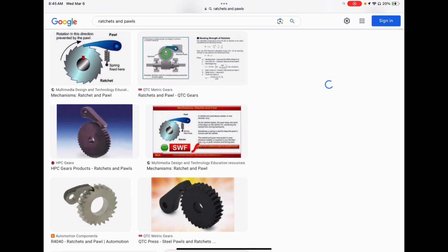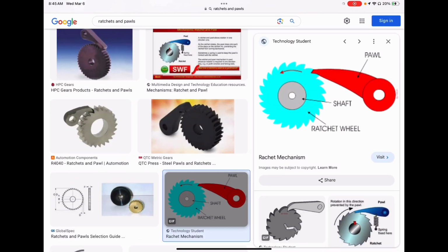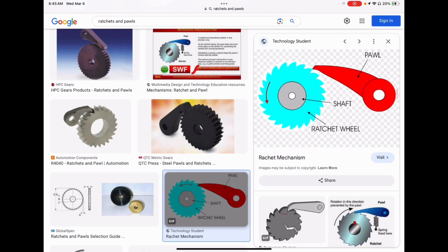We can see here that we have this motion that could be rotation counterclockwise, but if we were to try to reverse the direction, it would engage what we call the pawl. So the torque, or the motion we are trying to prevent, the pawl would have to take that load. There are other configurations here.